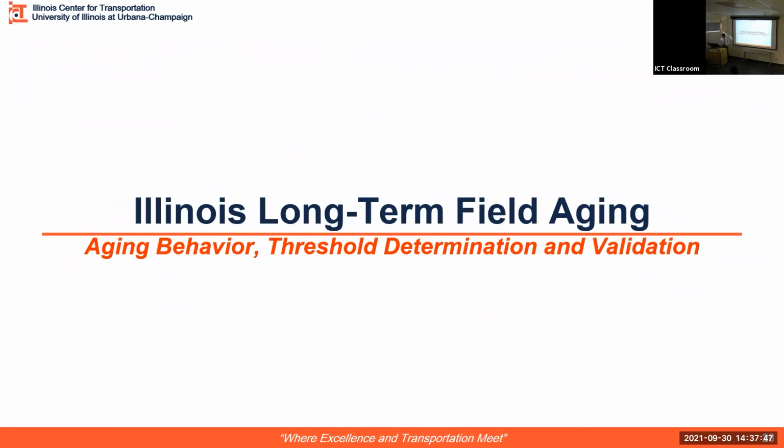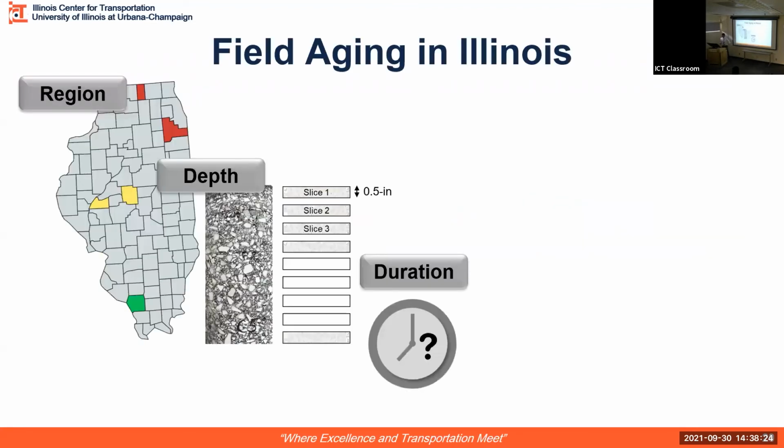So wrapping up, this is how chemistry complemented the rheological results for some of the modifiers, and some of the modifier testing helped us to see why some of the modifiers were not working, even though we didn't see that in chemistry, but we saw it in rheology. Now, the next question was to assess these binders for long-term aging. We really need to know what long-term aging was. Throughout the presentation, I was presenting that 2-PAV was distinguishing at this point, but we'll see whether that 2-PAV really represents long-term, or it's even more or less.